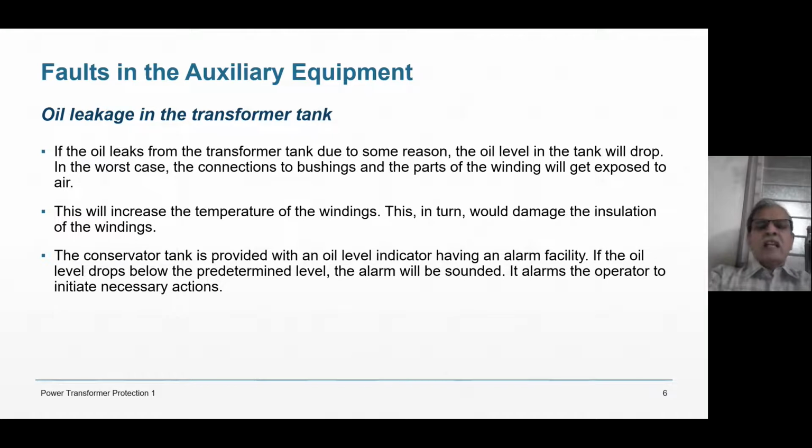And that has to be like that, because if the load increases, the oil level will go up, and if the load decreases, oil level will go down. And when oil level is going down, it is sucking air from atmosphere. Now when it sucks the air, moisture should not be sucked, right?